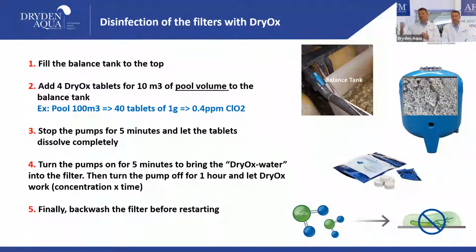Maybe you don't need 20 ppm, but if you go for 1-2 ppm, then chlorination in your pool, because maybe you break up the biofilms, but bits of parts are getting into the pool, and then you oxidize it. The chlorine dioxide will, in this process, lose a lot of its concentration. A part of it will be backwashed out, but also the rest will be oxidized in the water. And especially if sun is coming to the pool, then it's gone. But ideally, you do this process not when you're in operation. I wouldn't recommend this. Do it in the evening, when you close the pool.